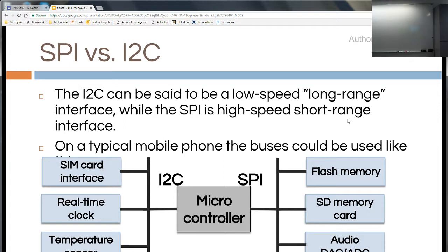It's a both ways kind of signal, and only one signal line. Then there's two-wire or the I2C, which is a nice, robust way of transferring signal. There's a data line and the clock line, which are both pulled up by resistors and open collector outputs on the devices. Then we have SPI.